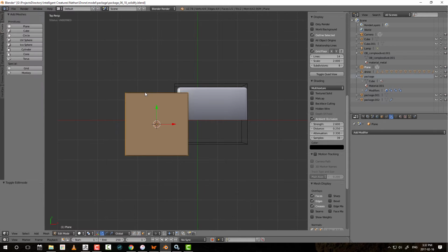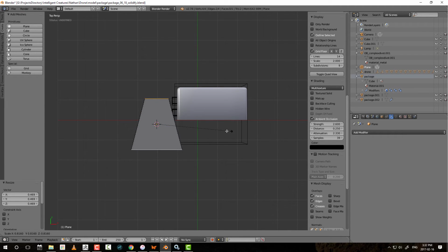Okay, now we're working on this plane. So first of all, go into Edit, Edge, Scale, and I want to make sure that this has a 45-degree angle, but I'm going to scale this and that together, and then I'm going to make sure that I am scaling on Y, and I'm going to scale this until, almost got it.